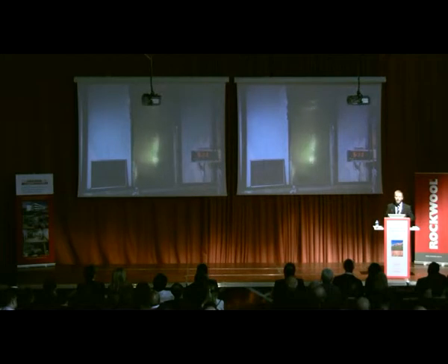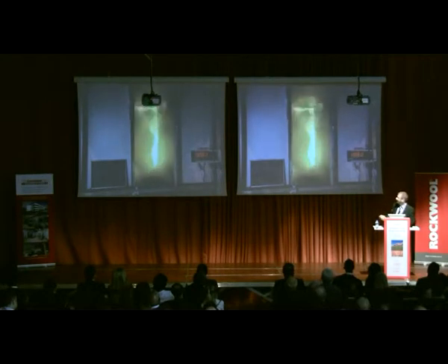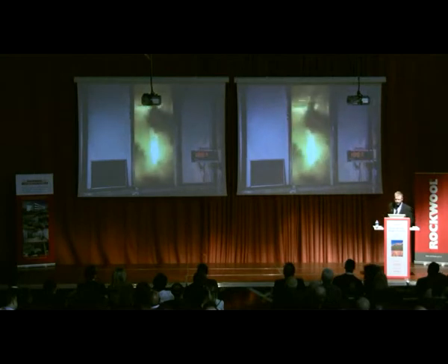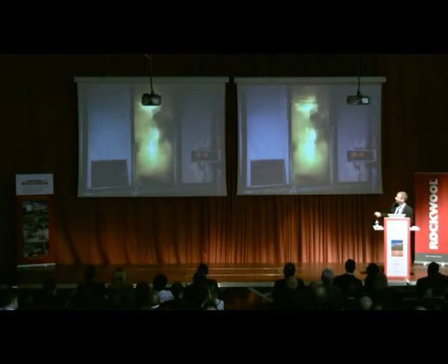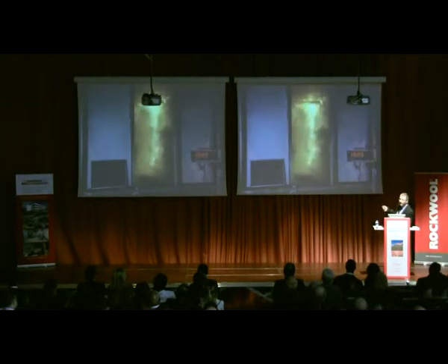Obviously, there may be no big difference if the fire exposure is small. But if the fire grows, you can see a much higher amount of smoke here coming to the fire site. And now, as the heating power is increased to 300 kilowatts, the height of the room is 2.44 meters. We can see that something is starting to happen here. We can see opening of the joint between the panels, and